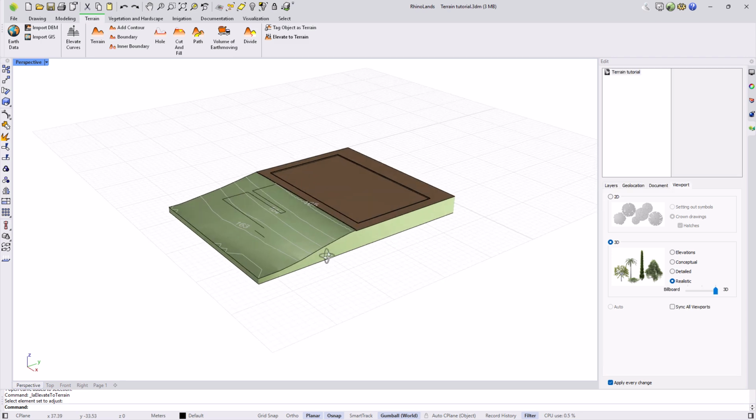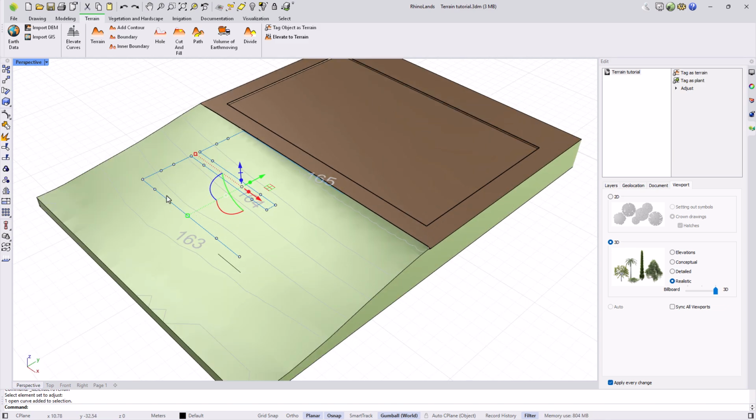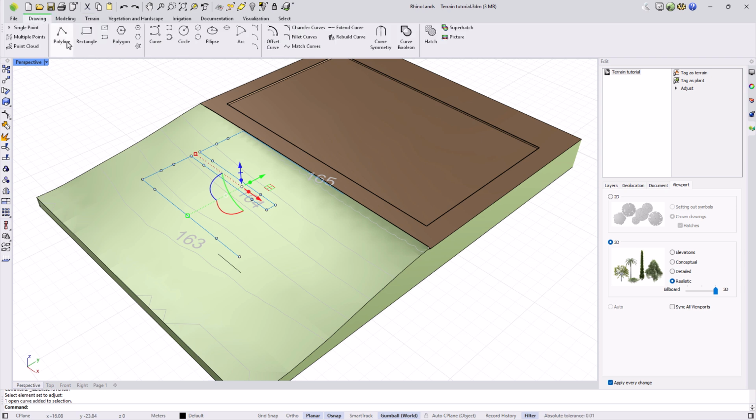I'm going to use this to optimize the slopes. What I'm going to do is make it so that only the horizontal ramp sections have a slope, and I'll use the vertical sections as landings. To do this, measure the height to cover from the highest point of the ramp on the ground, up to the smallest, that is, between the starting and ending point of the ramp.